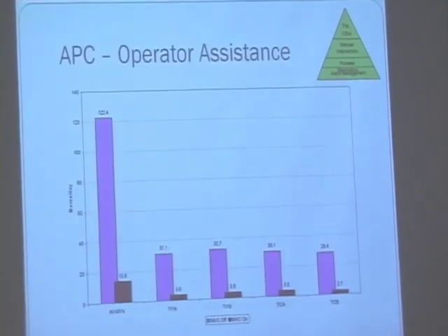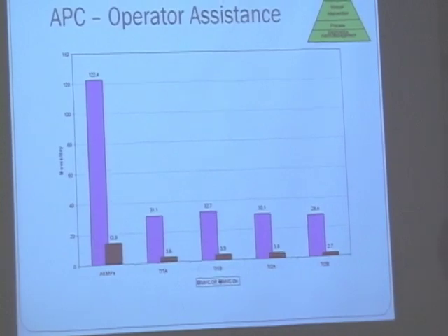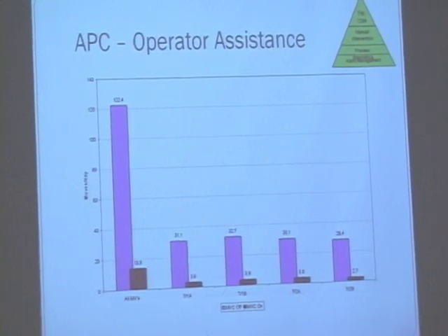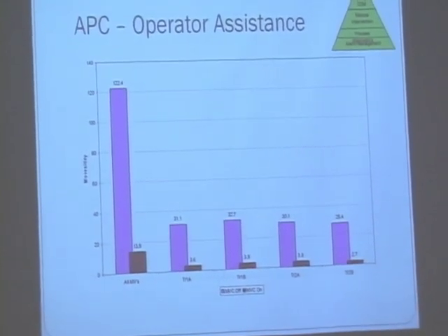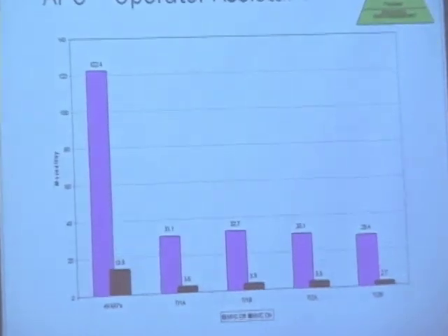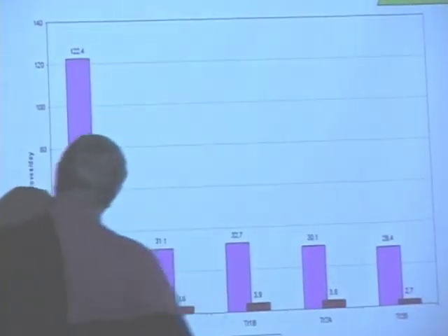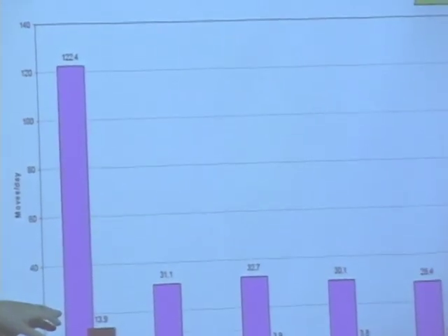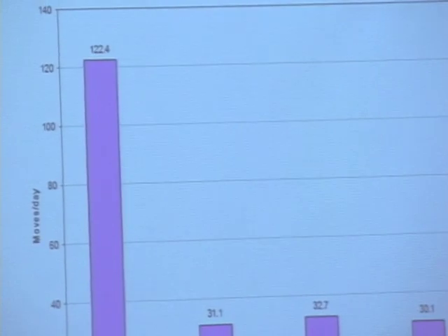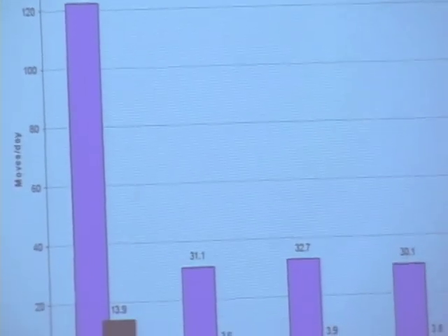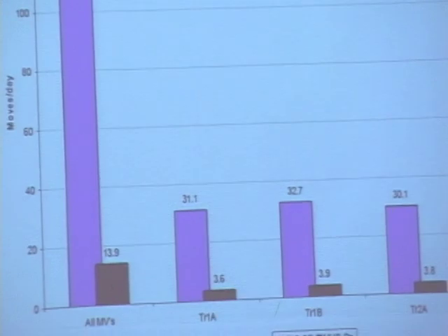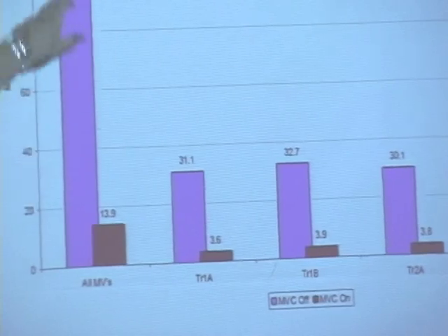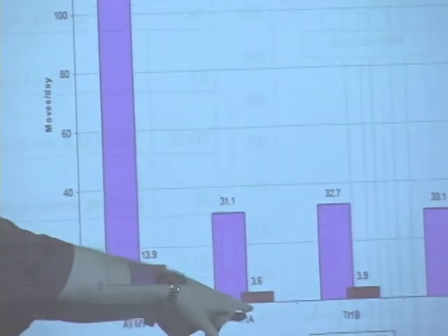And what we've seen as a company starts to address these issues, because it's important. If it's not in automatic control, your advanced control, you've just wasted all your money. You're not in advanced control, right? And at this one plant, these were the number of moves that the operator was making on a regular basis. And when we fixed the alarm system, this is now the moves the operator's making. What difference do you think that makes to your business? If you're not addressing alarms every 10 seconds, you're not making lots of moves, and it's in automatic, it's doing what it's supposed to do.